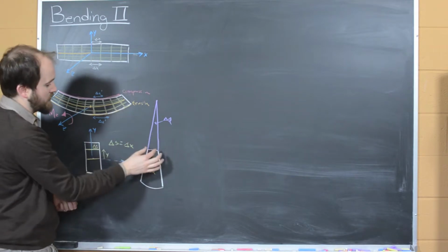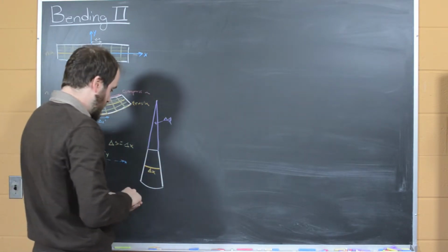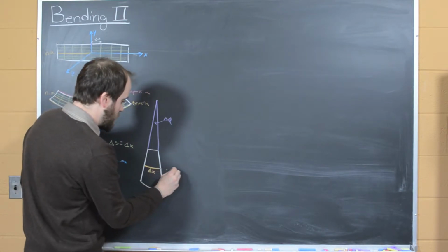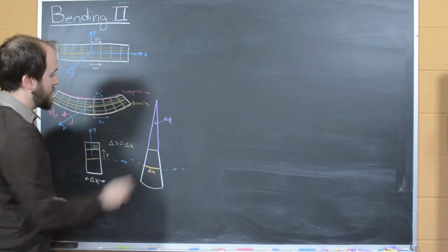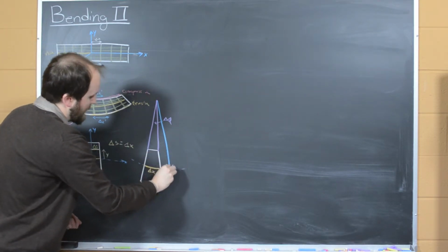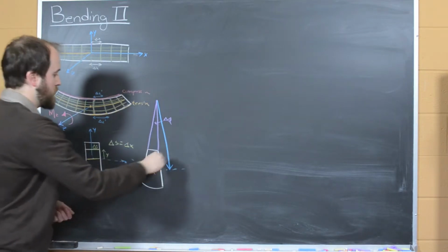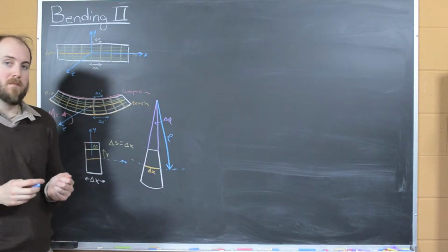And that angle is basically describing how much curvature is being induced from bending the structure. And the way that curvature is measured is we can think of that neutral axis of the beam. We can go back to the same point, and if we draw a line from that point to the neutral axis, this is described as the radius of curvature of this bent beam.